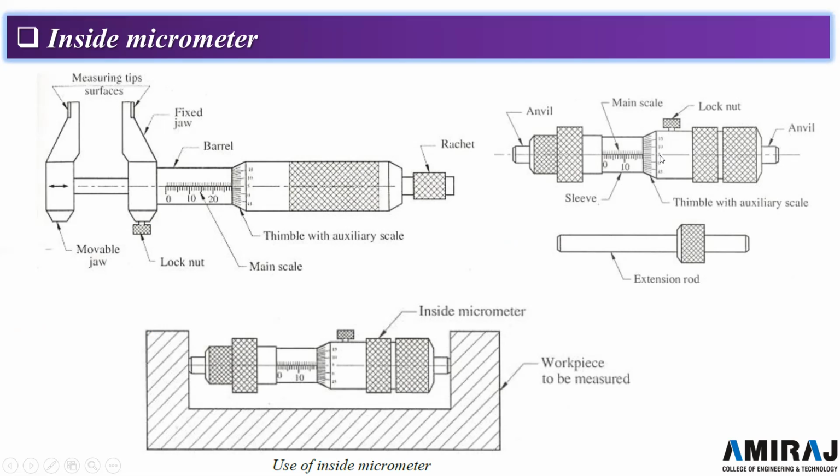Then the micrometer is checked for zero error with the help of standard size specimen whose internal dimension is known. Now the micrometer is adjusted at dimensions slightly smaller than the internal bore dimension or the diameter of workpiece. The micrometer head is then held finely adjusting the bore as shown in the figure, and the other contact surfaces are adjusted by moving the thimble till the correct feel is sensed.